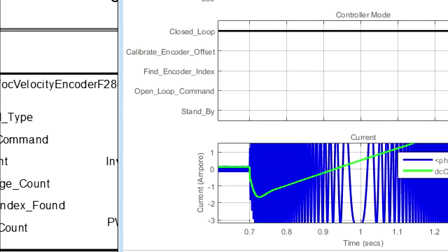Now, some boards can handle that. This one in particular can't. In fact, I know I can only push about a half an amp of current back into the power supply before it shuts down. See, if you remember, I said the original time I ran into this, the whole board just shut itself down, the power supply would go green. So I said, well, I should be able to design an algorithm that prevents this from happening, because I can't fix it in hardware at this point. The hardware already exists. And I can do this in simulation.